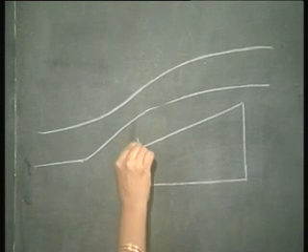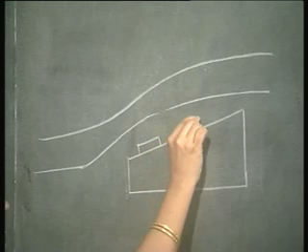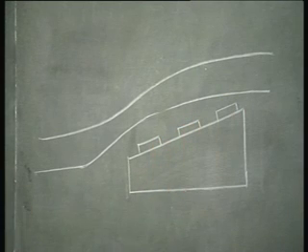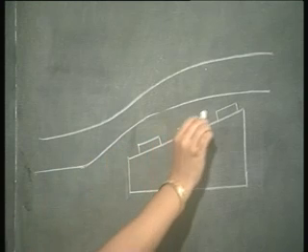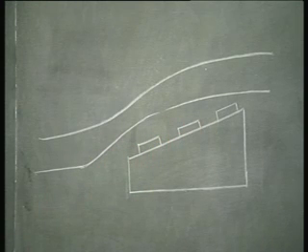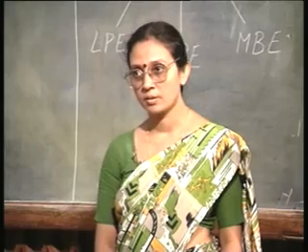Now, let me change the sample holder design like this. I have a tilted sample holder. The top surface is an inclined plane and the samples are kept like this, so that as you go down the length of the tube, the samples are placed higher, so that the effective width of the stagnant layer remains more or less the same, so as to ensure equal growth rate for all the samples.